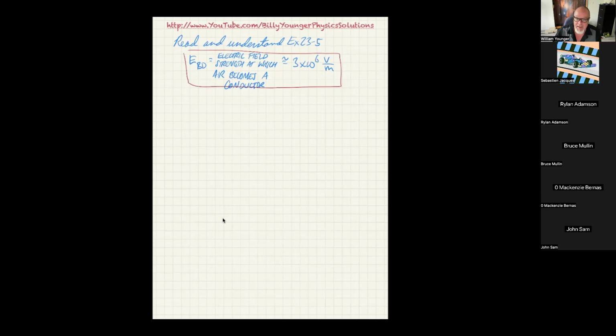So you're literally not even safe being a meter away from 3 million volts, because if you're grounded, your voltage is 0, and you walk within 1 meter of a 3 million volt wire, then the air looks like a fine conductor to the high voltage wire you walk next to. And in fact, lightning will find a way to go and hit you.